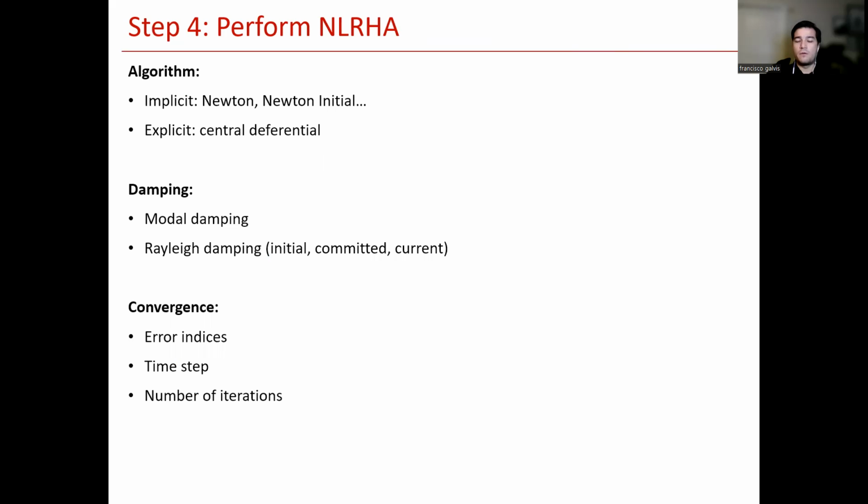If you have a multi-degree of freedom system, you need to define that damping matrix. And the damping matrix could be defined assuming modal damping or Rayleigh damping, those are the leading types of damping models. But there are other types of models like classical damping and things like that that are more detailed about how you can capture that aspect for multi-degree of freedom problems.